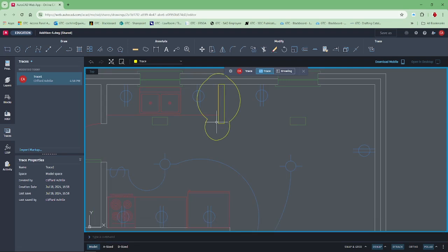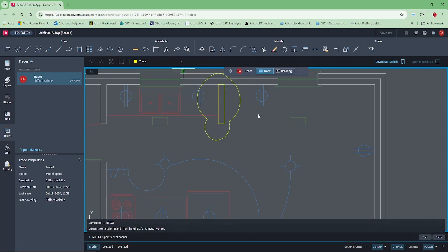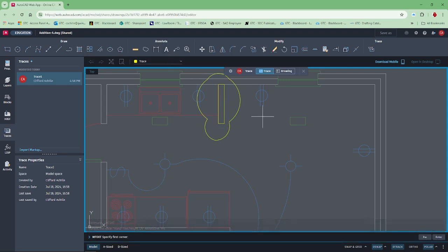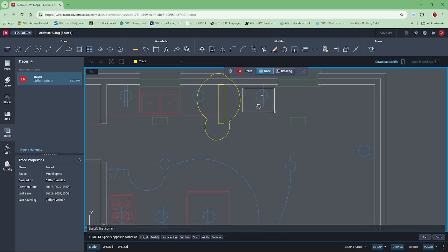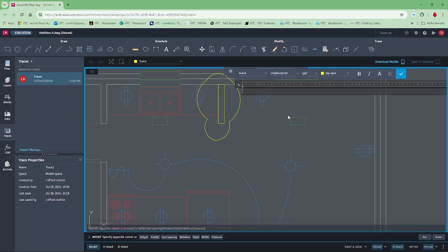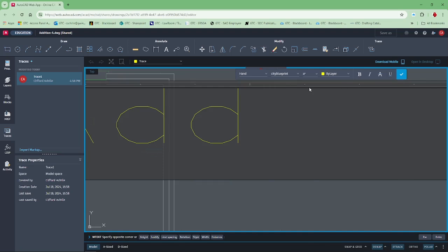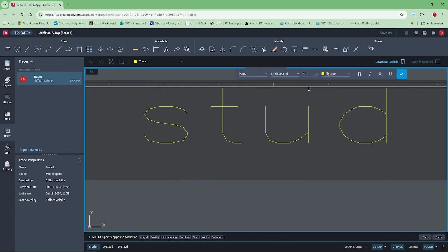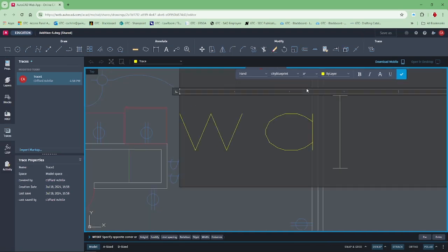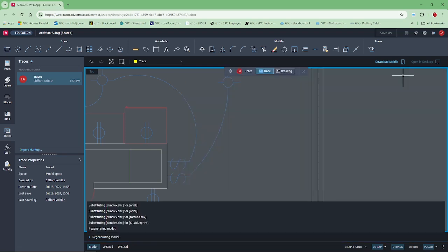In the Toolbar area, in the Annotate tab, click mText. In the drawing window, click 2 points near the cloud to create a text box. For the height, enter a value of 3, and in the text box, enter the text Add Stud Wall. Click the check mark to place the text.